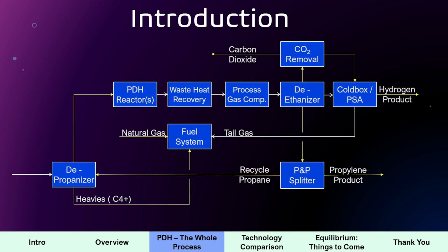So that's the carbon dioxide part, and there are so many solutions out there that can take care of that. We don't want to go into so much depth about it, but mainly they always use an activated MDEA solution, which is an amine solution. It basically doesn't take anything from the process gas besides carbon dioxide, which is what it's highly selective to.